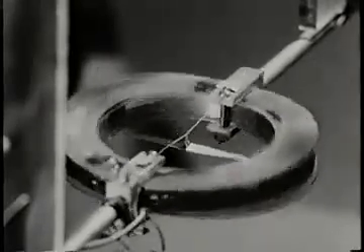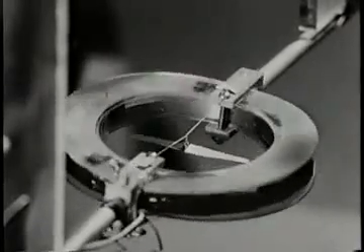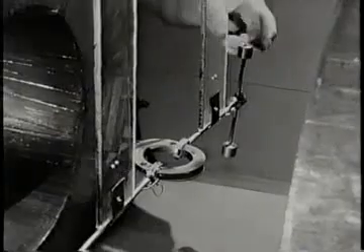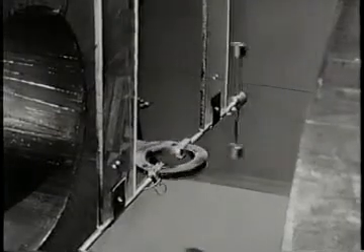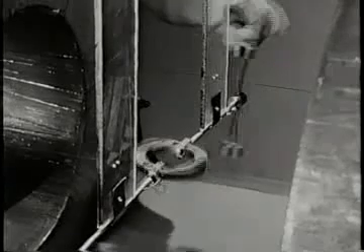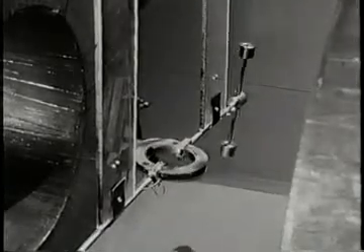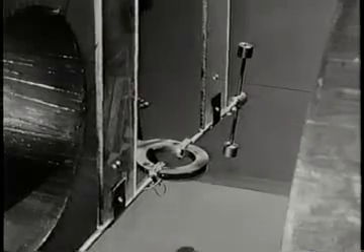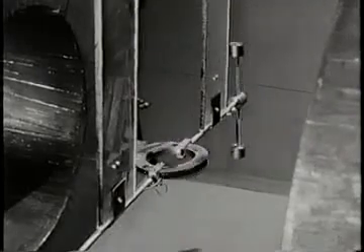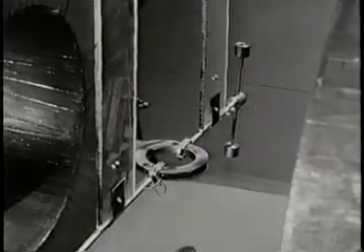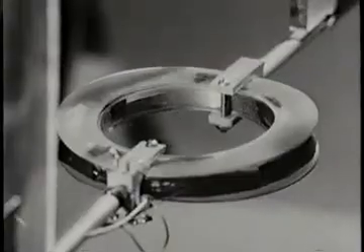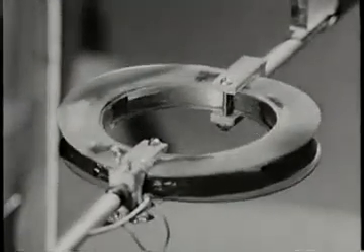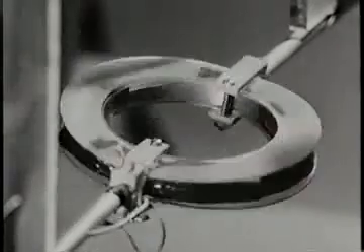If the coil is displaced, it oscillates. The damping is due to mechanical friction. There can't be electric dissipation if there is perfect conductivity. It's less than the magnetic relaxation time, so the field is strongly perturbed. And now the J cross B forces produce a restoring torque, which, for small inclinations, is proportional to the angle of inclination, like an elastic restraint.